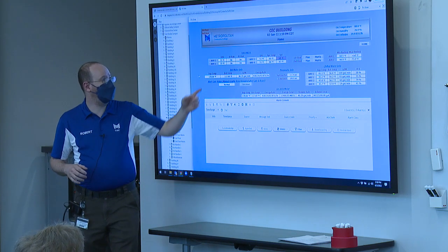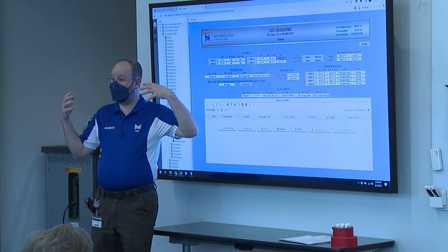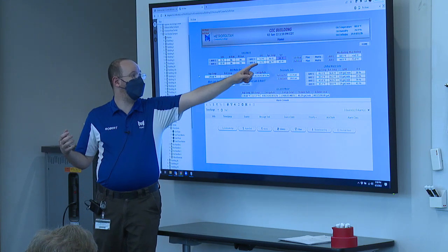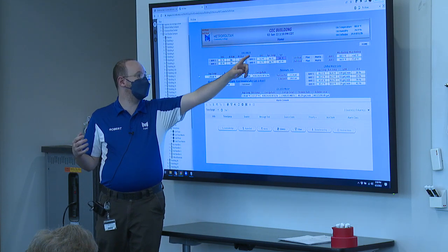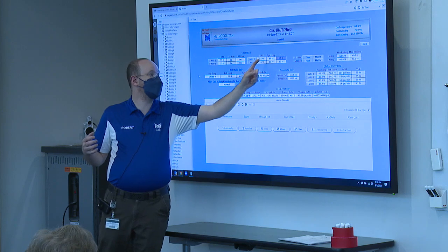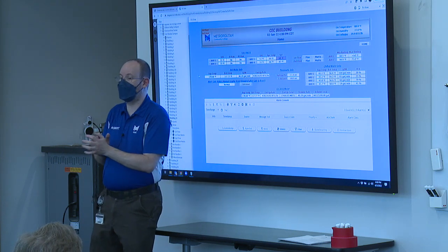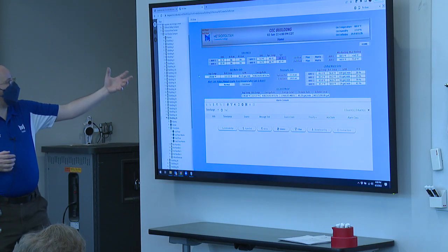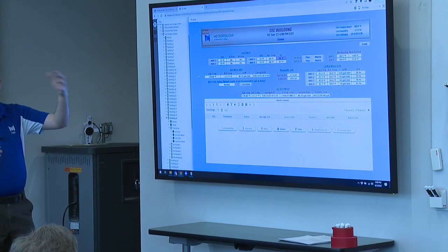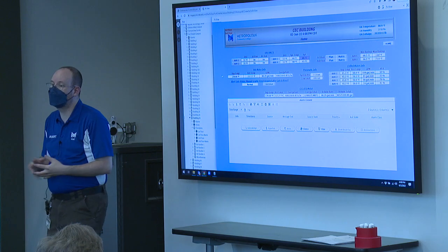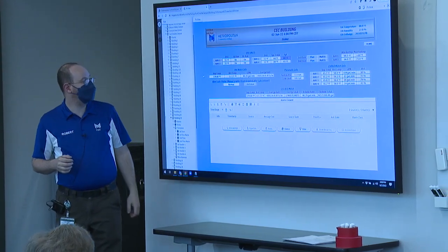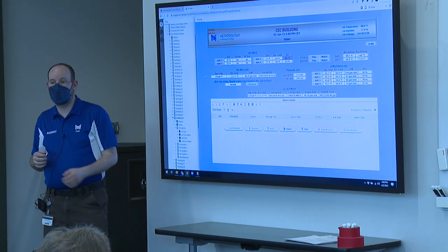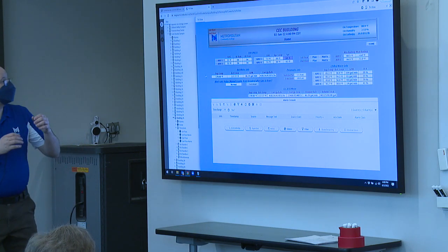Okay? Air handlers 3 and 4 are big single zone units. So instead of the fan statuses, they've got discharge air temperature and space temperature and setting. Just a quick glance. Hey, how's my building look? Nothing jumps out at me as terrible. Away we go.